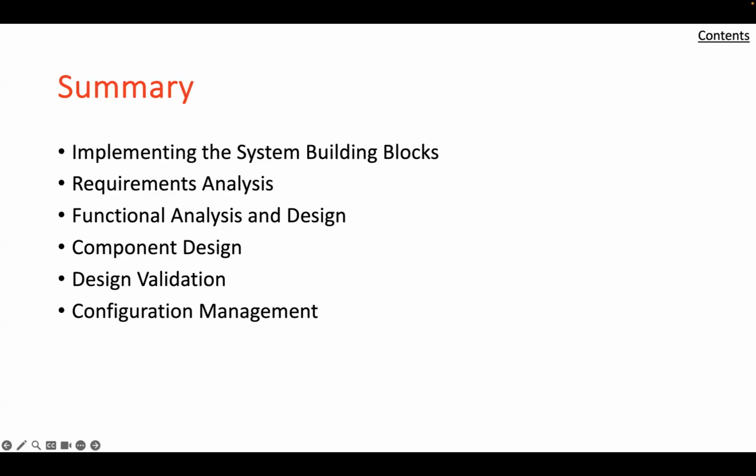Test planning must be done early since test equipment requires extensive time to design and build. Additionally, test costs must be allocated early to ensure sufficient resources. Finally, test planning is a team effort. Development test is part of the design process and should start accumulating reliability statistics on failures. These test failures are often due to test equipment or procedures and should be planned for, since changes after critical design review are subject to configuration management.